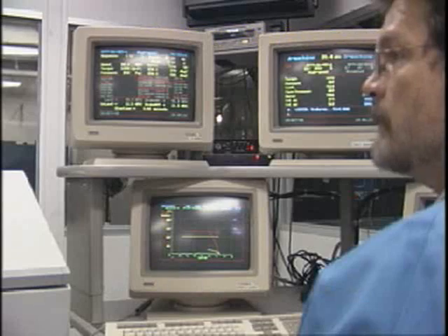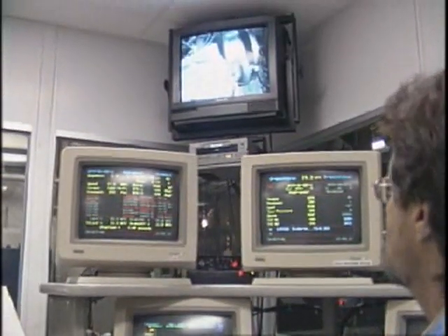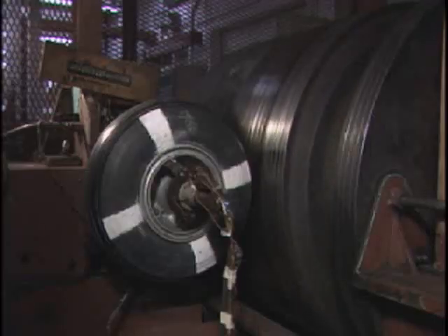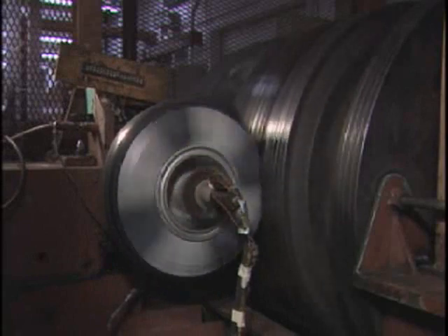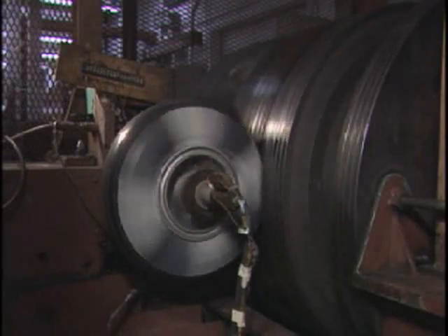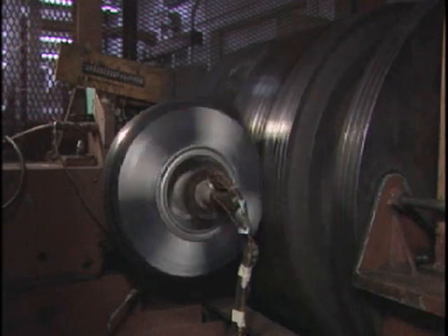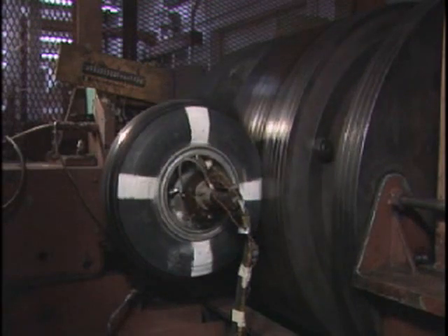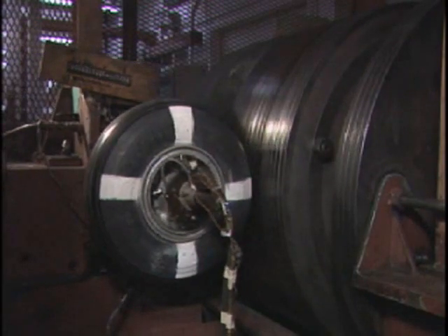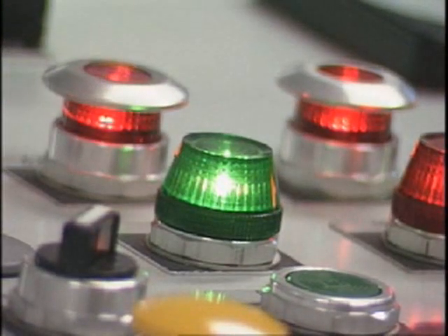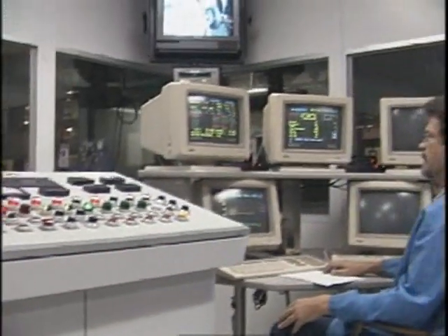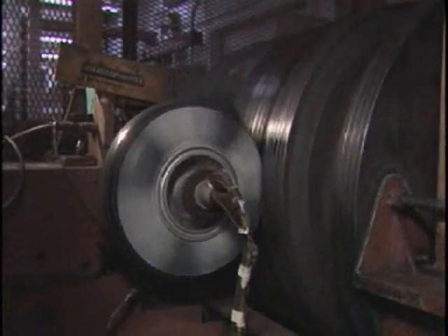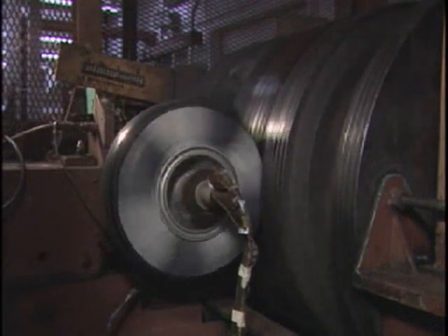In the initial tests, we used two different taxi stop speeds, but the same number of taxi stop events. Interestingly, the test with the higher taxi stop speeds resulted in a very significant reduction in wear. The higher taxi stop speed with its higher temperatures caused the large abrasive particles to transform faster into the finer film-like particles. As this film develops, wear decreases. In this testing, allowing the taxiing aircraft to accelerate to a higher speed before applying the brakes heats the carbon discs quicker and shows less wear.